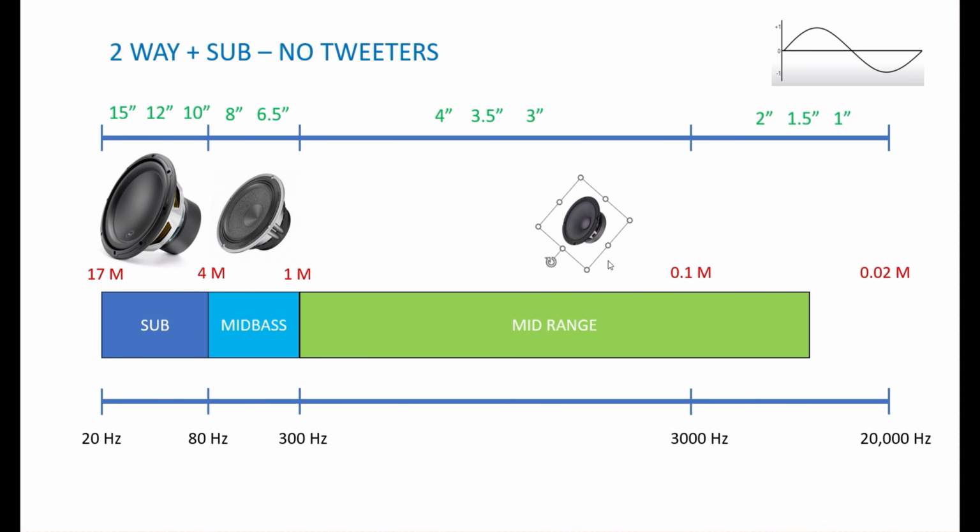So quite often these will be wideband speakers. They'll have specs that say you can play from 50 hertz all the way to 20,000, or something like that. But same as the previous example, they might be able to play that. Will they play it well is another question, right? Wide bands won't be 4-inch. They're probably 3-inch or maybe even 2.5-inch, and they're a compromise between a tweeter and a mid, trying to get a mid-range to play super high. But once again, you can have a decent system with it. You just be aware that the top end is going to suffer, right?